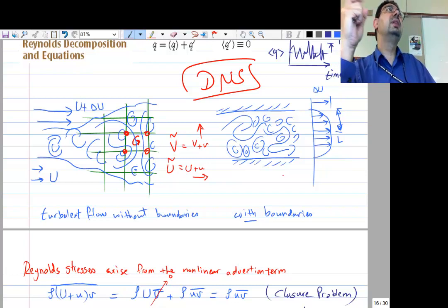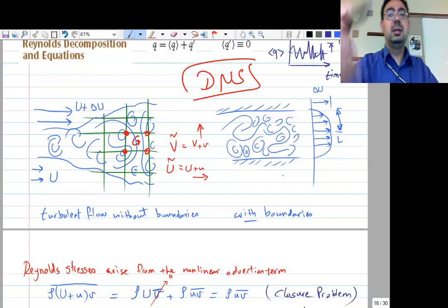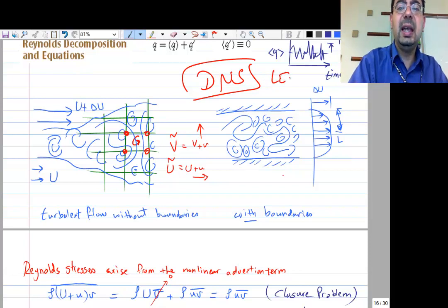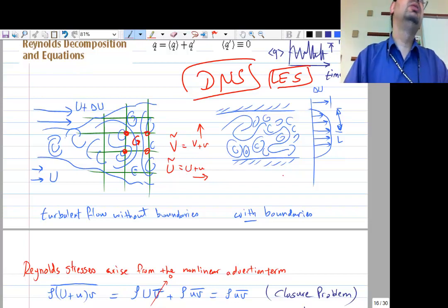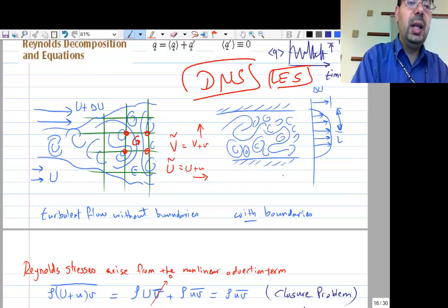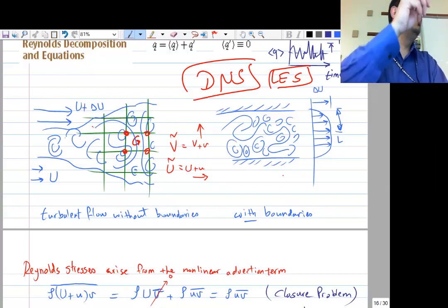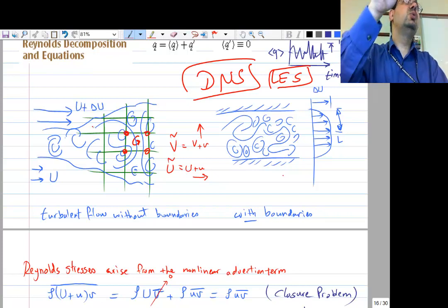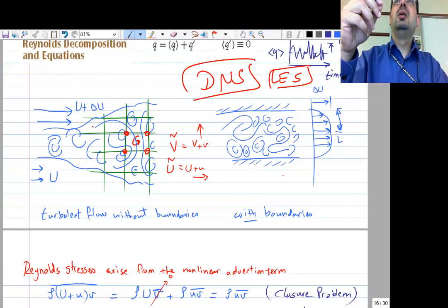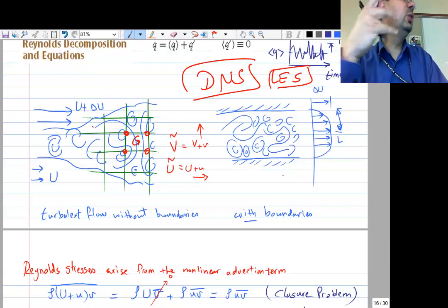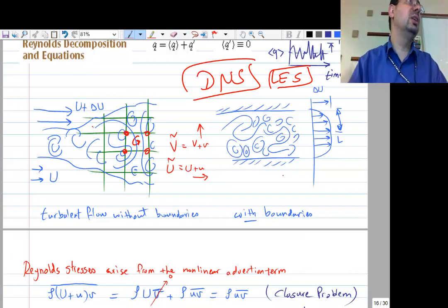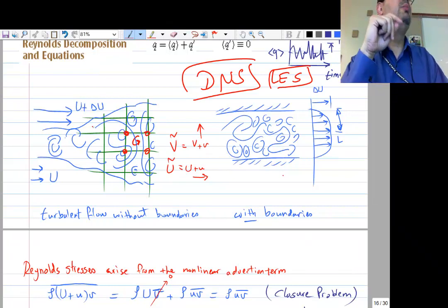Right? So what is the next step? The next level is LES, large eddy simulation. And that name could not be better chosen. Large eddy simulation says, let's not make the grid solve the tiniest eddies, we can skip them. Why? Although there are a lot of things happening at that small scale, that's where all the energy is being lost into viscosity. But they can model that effect.